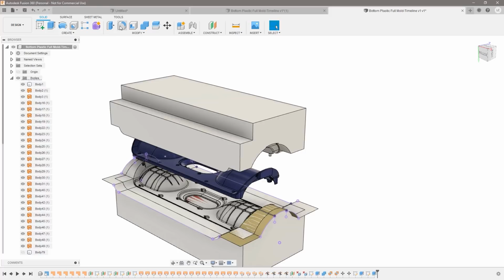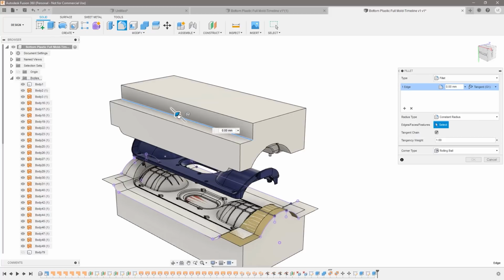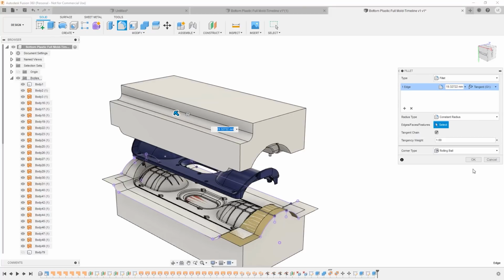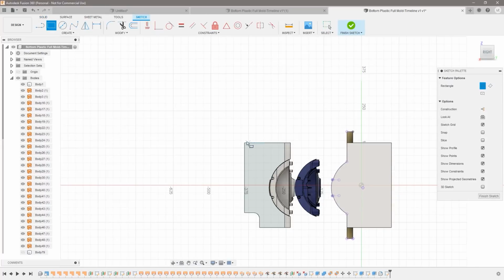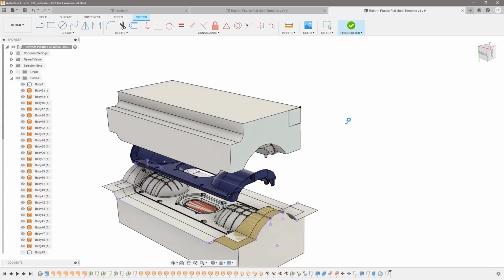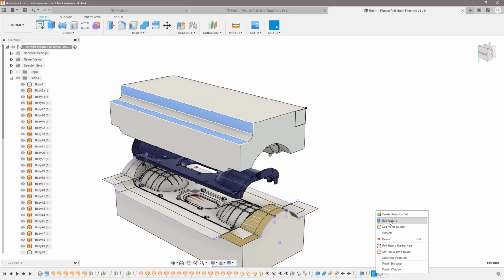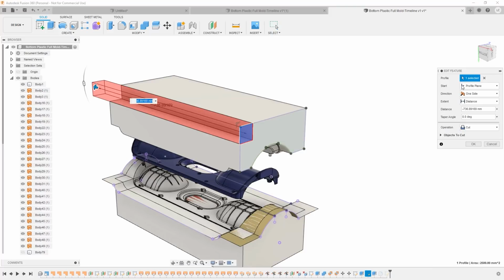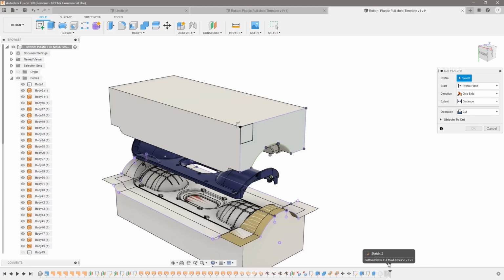Another thing you might see is if I go ahead here and add a fillet, let's add a fillet, something like this, to this part. This is all good. Well, I could create another sketch on the opposite corner. Let's make that 50 by 50. And just as I redefined our sketch to the right plane, I could go ahead here and say I want to edit that feature that was the original cut. And instead of selecting that sketch, I could select that sketch right there instead, right?